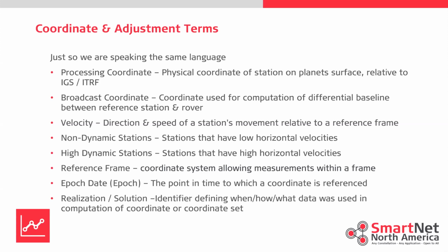Broadcast coordinates. These are the coordinates that are used for computation of differential baselines between the reference station and the rover. Okay, so this is what we send out to you in the RTCM message that says what you're calculating your vector off of.